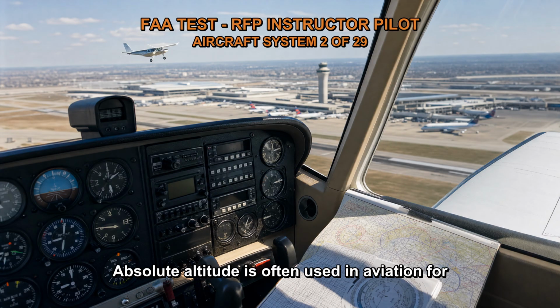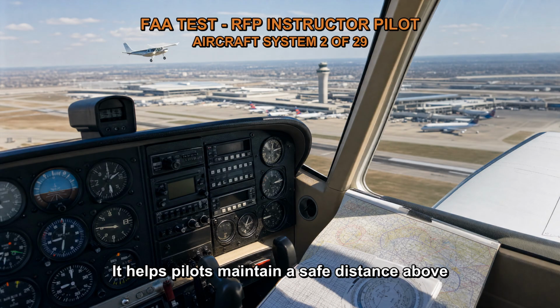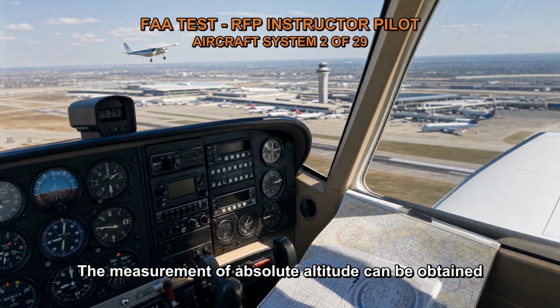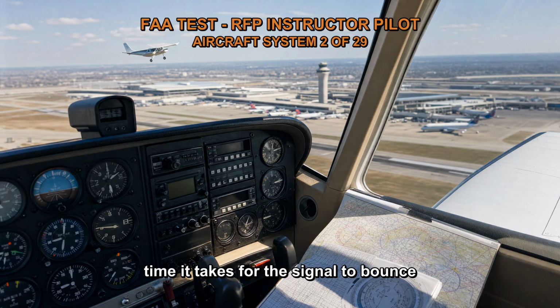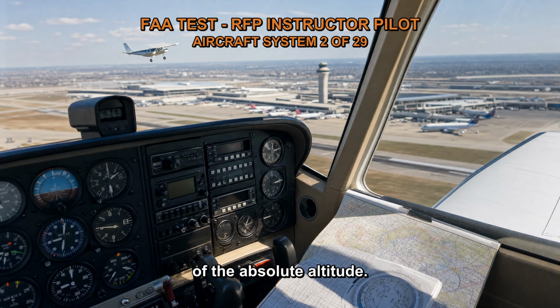Absolute altitude is often used in aviation for terrain clearance, obstacle avoidance, and low-level flight operations. It helps pilots maintain a safe distance above the ground and ensure clearance from terrain features such as mountains, buildings, or other obstructions. The measurement of absolute altitude can be obtained from various sources, including radar altimeters, which directly measure the vertical distance between the aircraft and the ground. Radar altimeters use radio waves to determine the time it takes for the signal to bounce back from the surface, providing an accurate reading of the absolute altitude.